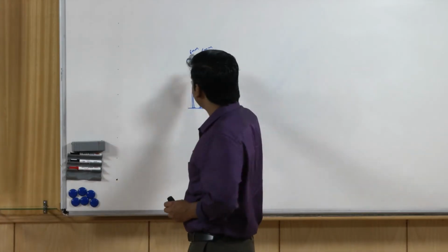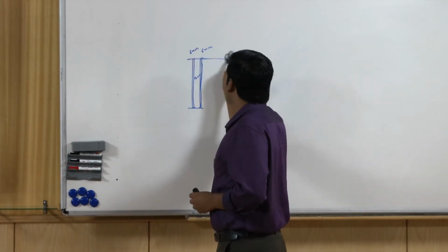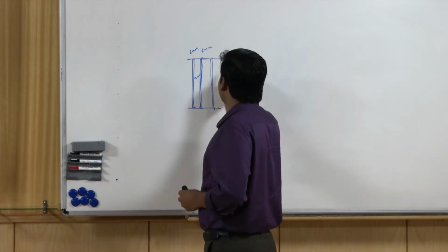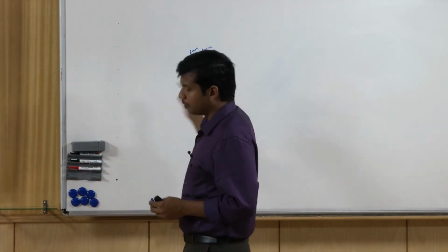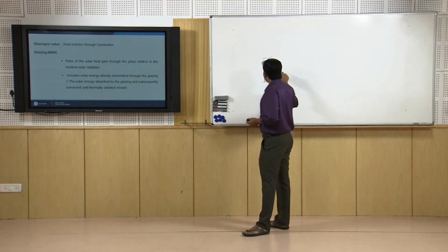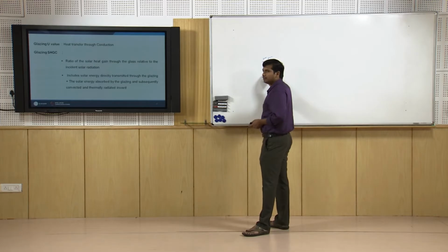As you increase the number of layers, with a triple glass system adding another layer, the U value keeps coming down. It essentially tells you how much conductive heat flow happens. So this matters. Then the next is the conductive property of the air gap, or if it is inert gas filled, like argon filled, then this brings down your U value.